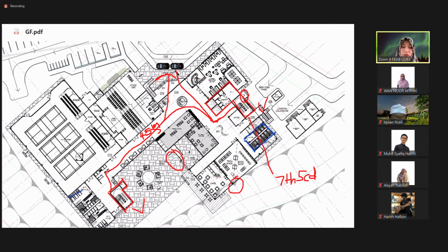Okay, bear in mind, in your building services, based on the occupancy, the number of people who will occupy the building, in the building bylaw, at the back appendix, you have to refer. There, in certain clauses, they mention how many cubicles you need to design for toilets, for washroom, based on occupancy. That you will have to calculate.